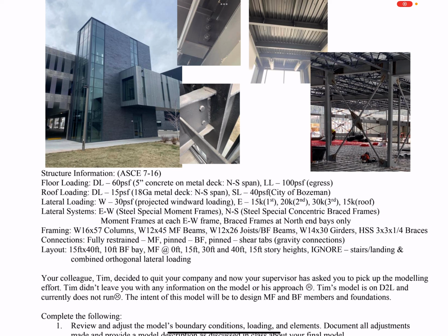So we've basically cut out portions of the top and bottom flange to weaken this member right here. So when this thing gets pushed over in the east-west direction by wind or earthquake, this thing's supposed to go completely plastic. It's supposed to just bend, right? Turn into putty, right? A lot of energy dissipation. And we want it out there, so we then reduce the strength of the beam out there.